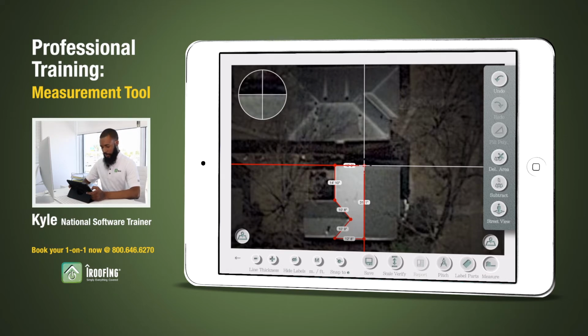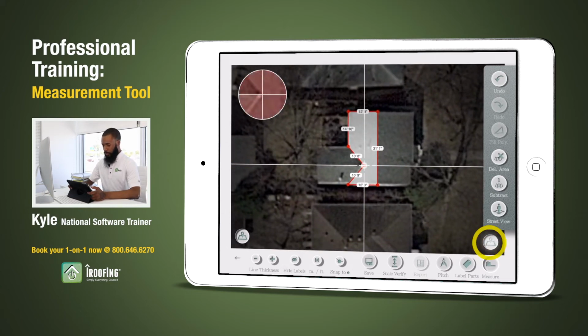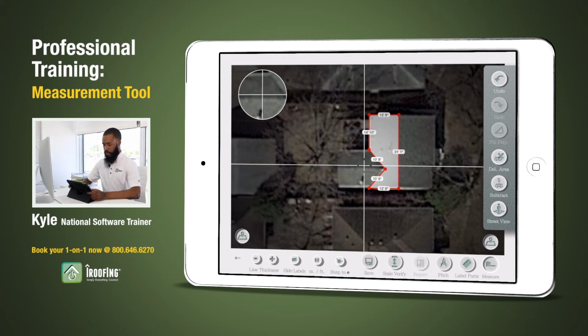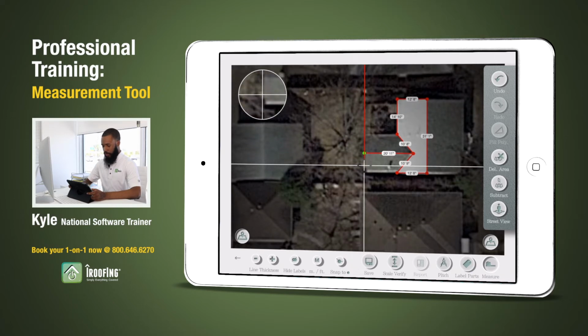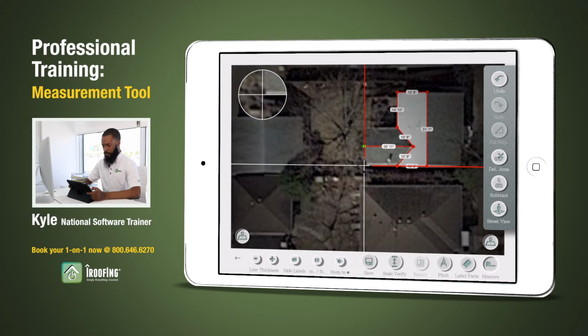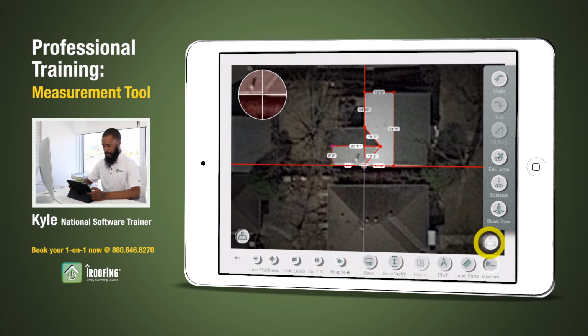Now for our next area, we'll begin from the back of the ridge on the gable that's at the back. We're going to hit the marker button on that point to let the app know that that dot will be a part of the next area. Then we're going over to our left, across this ridge, until we reach the rakes on the opposite end. And we'll place our marker here. Now I need to go down the rake and towards the eave on the side. Place a marker there. Then over to my right, across the eave, to place a marker at the bottom of the valley. And that will complete that area of the roof.